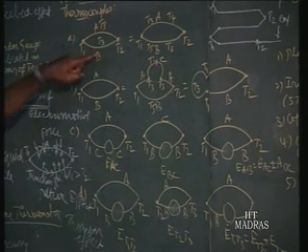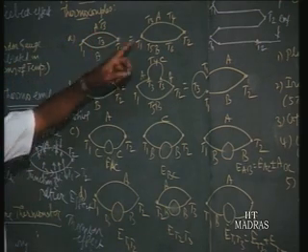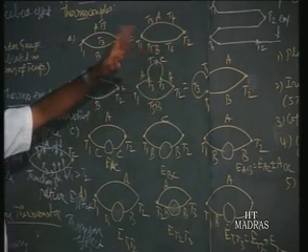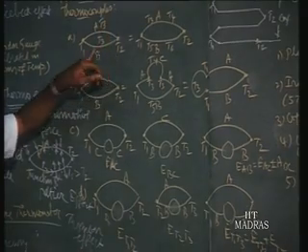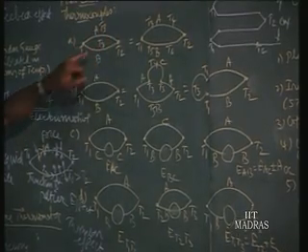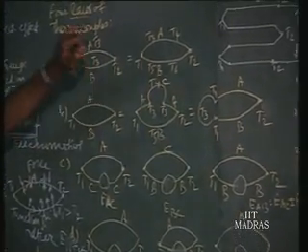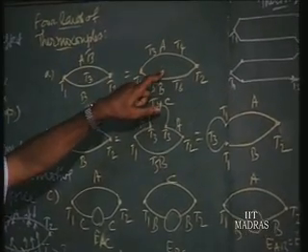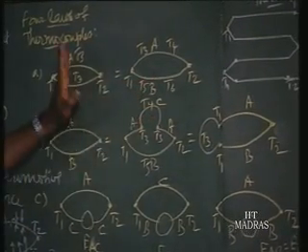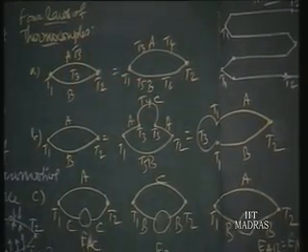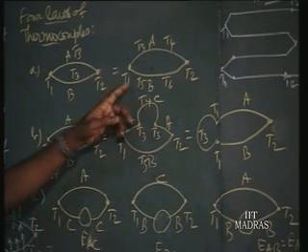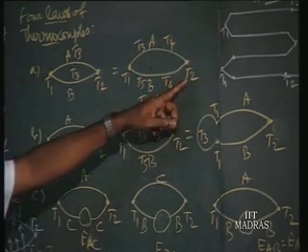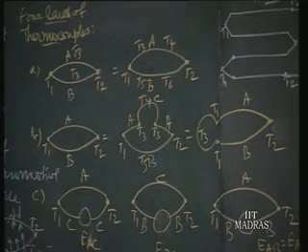Even when the intermediate temperature happens to be T3, or T3, T4, T5, T6, something like that, you find the voltage developed in the first circuit is same as the voltage developed in the second thermocouple circuit. That means intermediate temperatures of these 2 wires will not affect the EMF developed due to the temperature difference of T1 and T2 in the 2 junctions. Intermediate temperature can be anything.